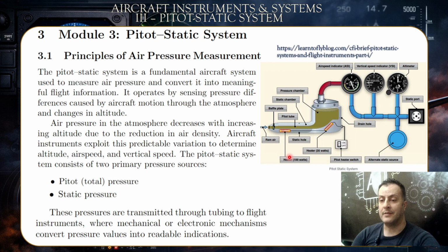Because the actual real airspeed was much lower than the one indicated, and the one indicated was too high, due to the fact that the blocked pitot tube led to a very wrong measurement, giving a very inaccurate and overly high airspeed.